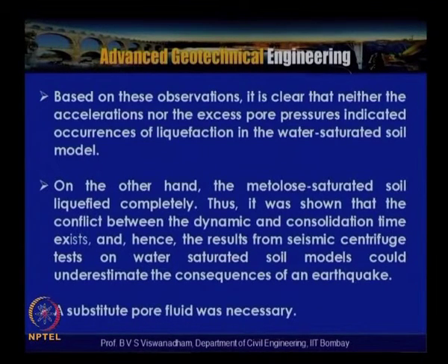This indicates that if you are checking a structure resting in a water saturated model and tested in a centrifuge, it may lead to conservative results, wherein we end up saying that the structure is safe from the liquefaction point of view.